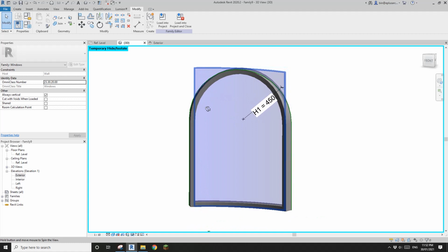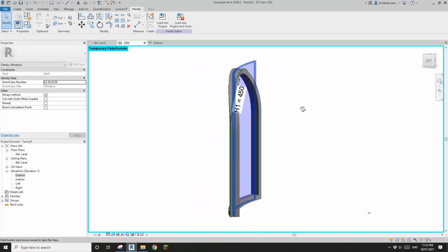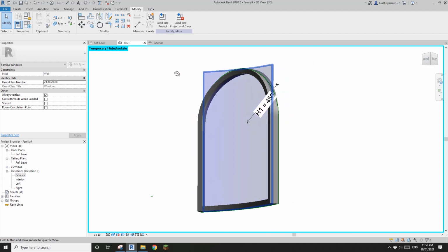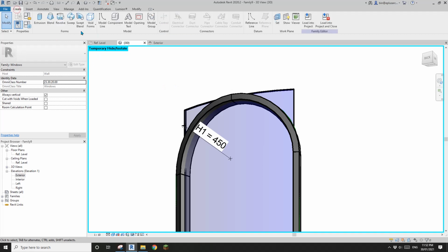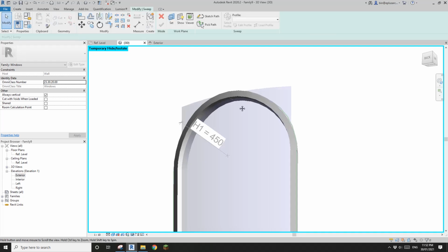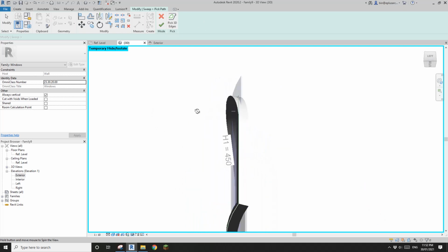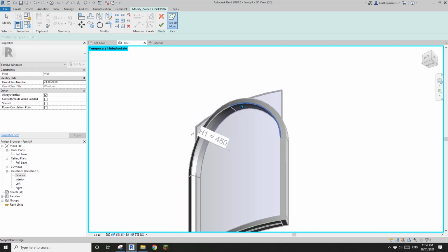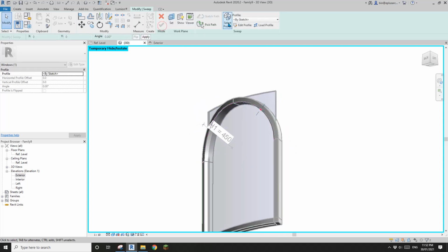To cut this part, it's really hard to do this, but I think I worked out a way to do it. Just use a void sweep. So let's do it. I'll create a solid sweep for now. Okay, so pick path, and let me think which one should I pick. Doesn't really matter. I'll pick this one and this one. Okay, and then finish and create.